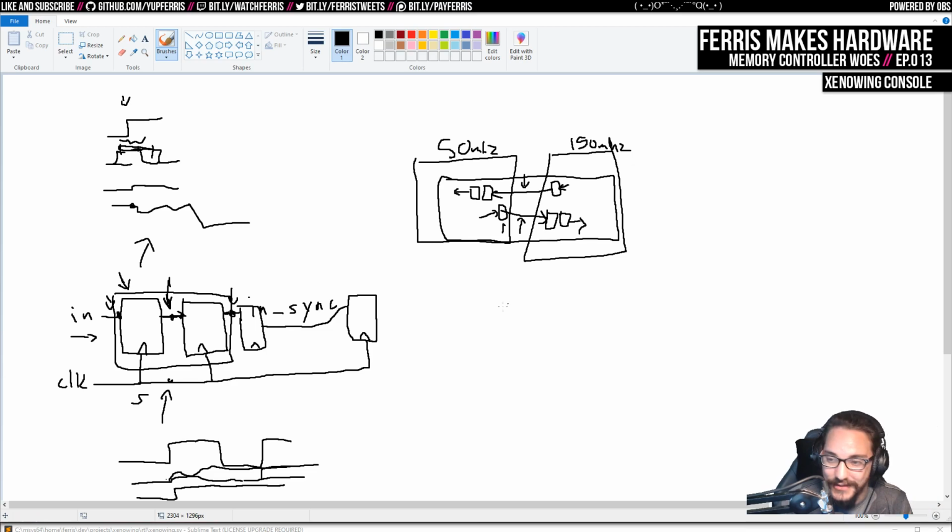Because this is actually one of the bigger problems that I don't think I mentioned, is that when you have multiple signals coming in, so let's say you had a clock and 3 data lines, and these you need to synchronize into a certain clock domain. The obvious solution would be to do these synchronizer chains on each one of these bits. And this doesn't work, by the way.